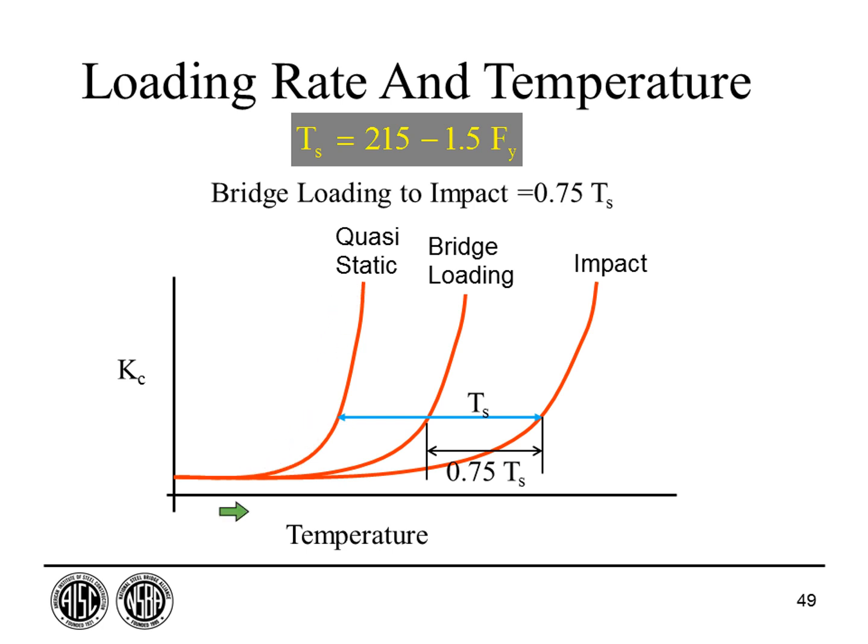Now if I do that same steel and I test it at an impact loading, and that would be with an impact where the maximum load occurs in milliseconds, you get a curve like this. So if I'm at a temperature like at this level, if I do it at an impact load, I have this toughness.